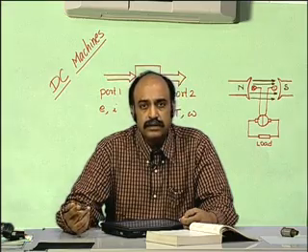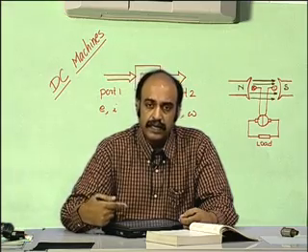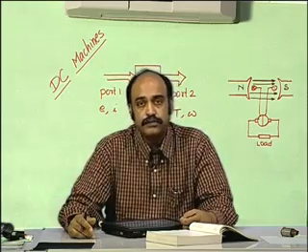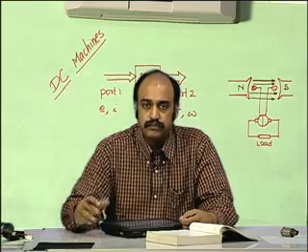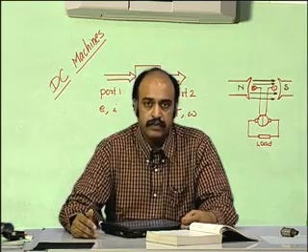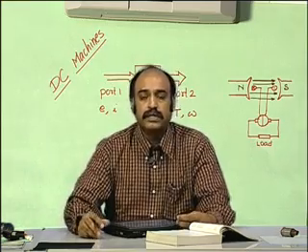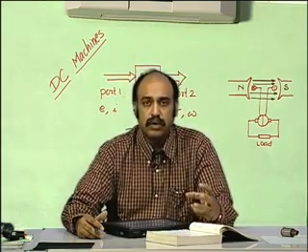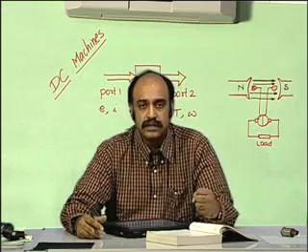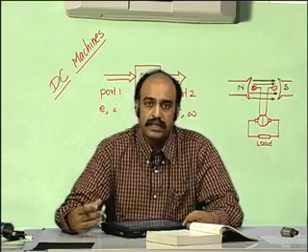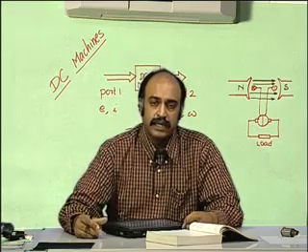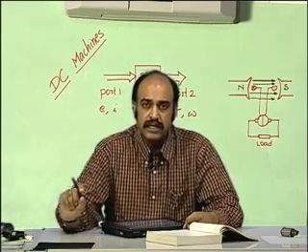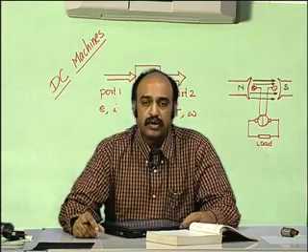Likewise, the flow on the electrical side is related to the across variable or the potential variable or the effort variable on the port 2 side. Another point to be noted is that in a DC machine, one port is electrical in nature, meaning the quantities applied to one port are electrical quantities, and the quantities applied in the other port are mechanical quantities, because it is in the mechanical rotational domain.